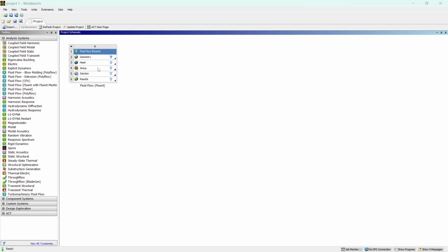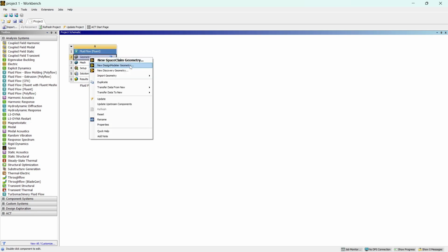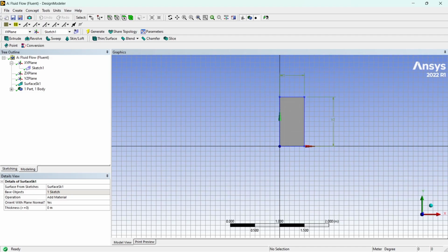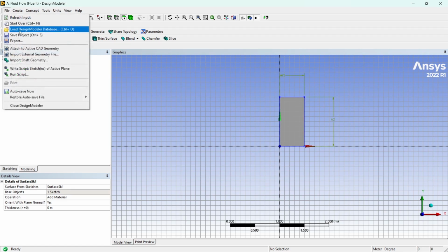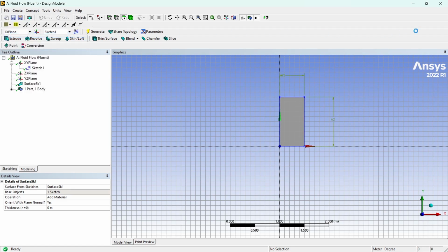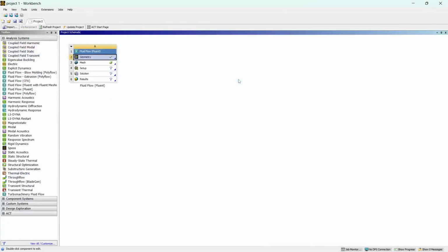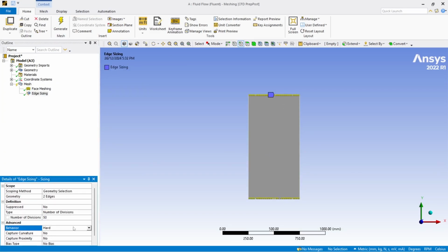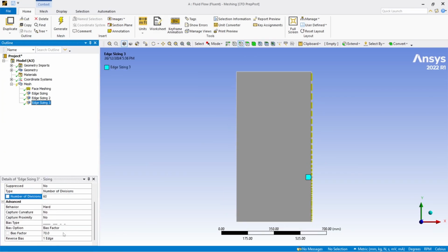In this experiment, we focus on investigating the effects of airflow velocities at 2 m/s and 2.5 m/s on the velocity profile and boundary layer thickness. We will walk you through the process step by step, from geometry creation and meshing to setting boundary conditions, running the simulation, and analyzing the results. I will fast forward to the velocity inlet part.